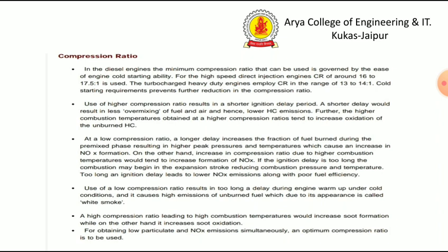On the other hand, the increase in compression ratio, due to higher combustion temperatures, would tend to increase formation of NOx. If the ignition delay is too long, the combustion may begin in the expansion stroke, reducing combustion pressures, and too long an ignition delay leads to lower NOx emissions along with poor fuel economy or efficiency.